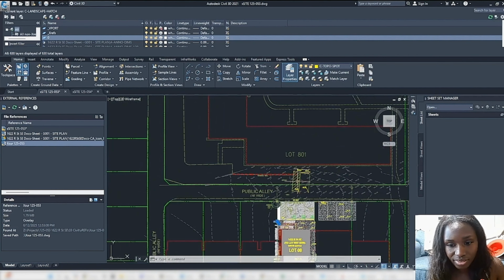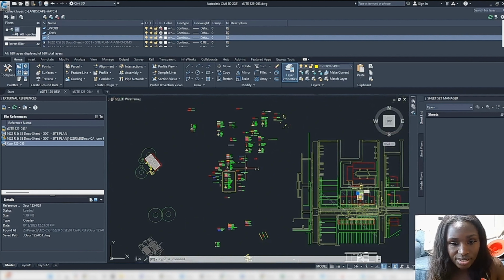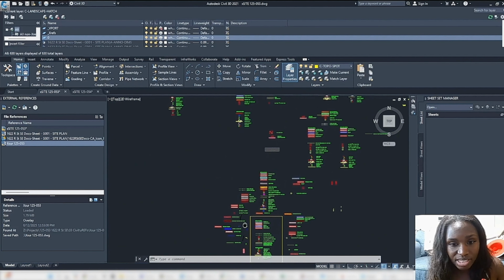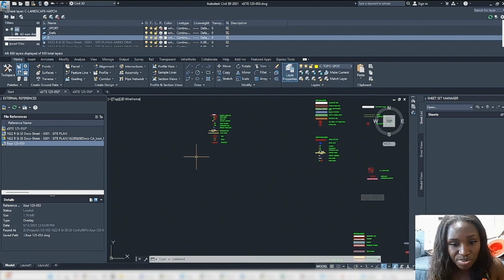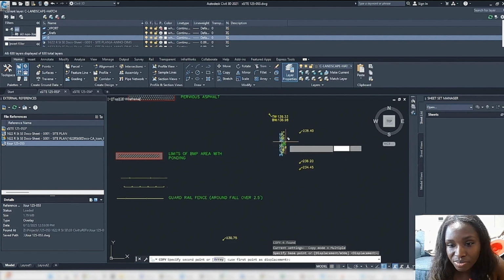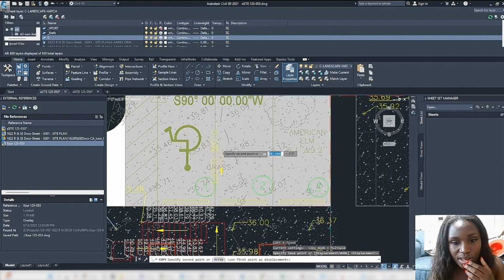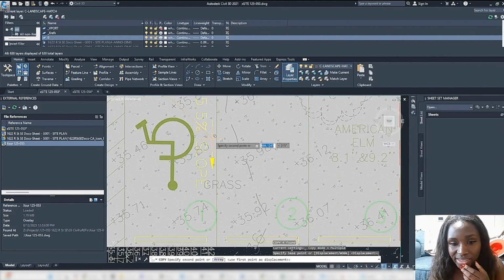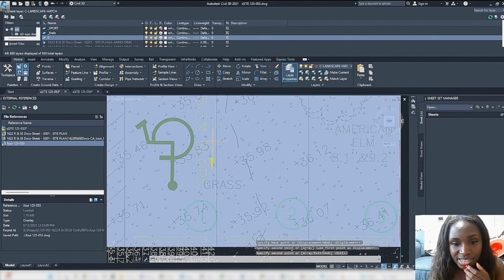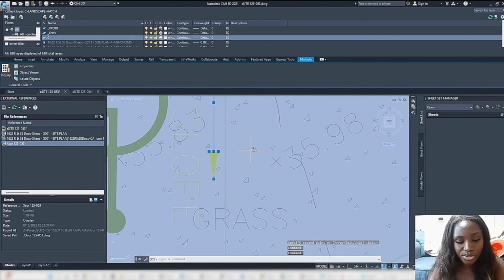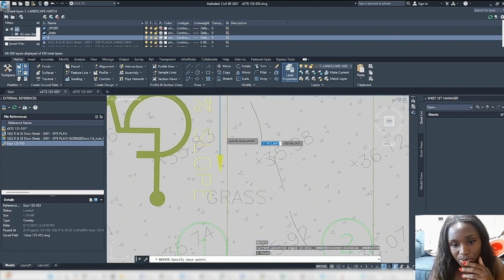Another thing is, for ADA parking spaces, they can't be too steep. We always design them with room to spare. I'll design them at about 1.85 at the tightest, but here I think we can be even more conservative and probably do 1.5.